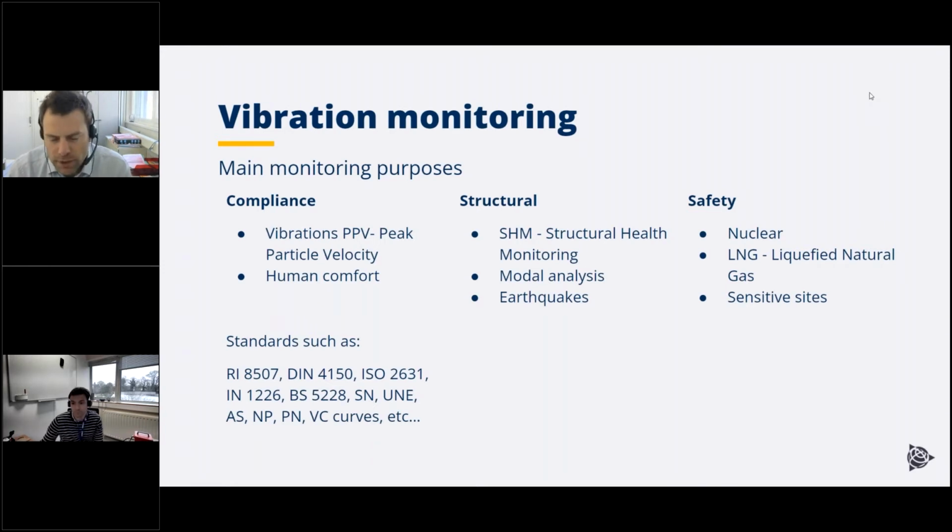So obviously to liabilities, who is responsible for the damage to the structure. And by analyzing and monitoring the vibrations, you can define if there were too high vibration levels or not. And maybe with that, structural SHM applications also have some modal analysis, to understand how the structure moves and have some different modal shapes, to understand if your design models are respected and compliant or not, and if the structure was properly built or not.